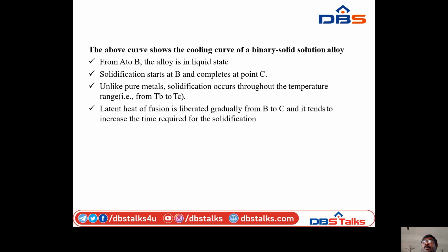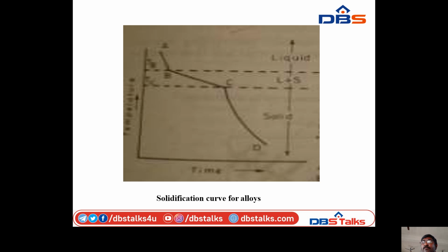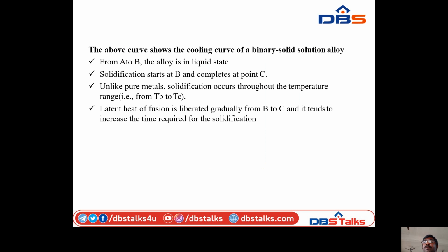Next, unlike pure metals, solidification occurs throughout the temperature range from TB to TC. Next, latent heat of fusion is liberated gradually from B to C, and it tends to increase the time required for the solidification.